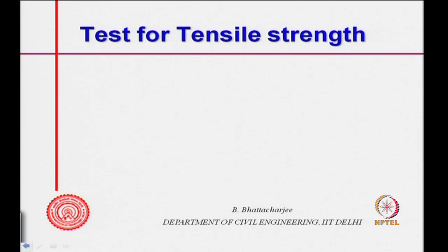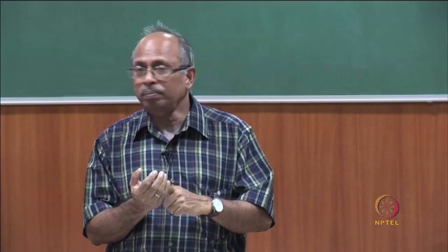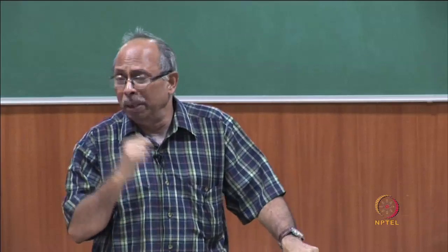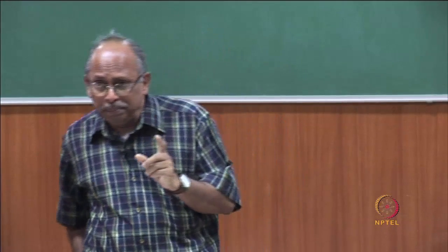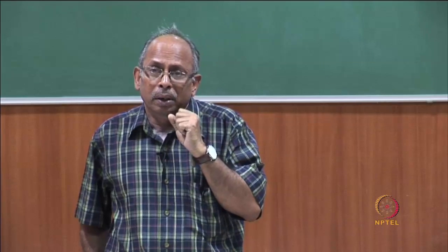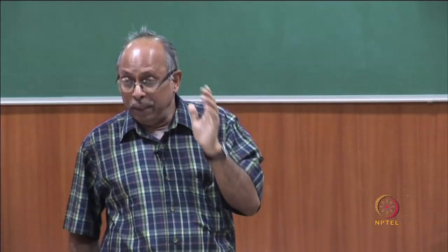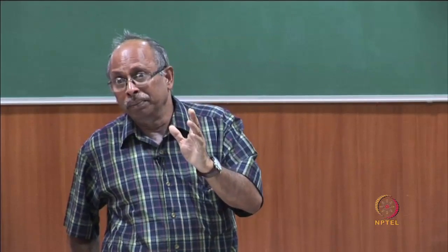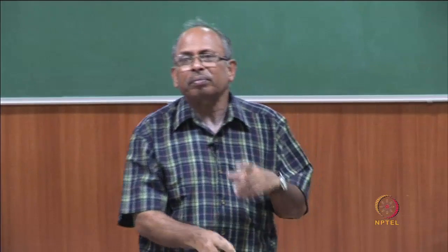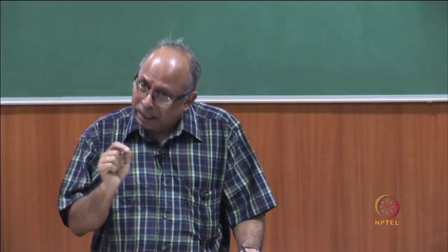So, what we have seen for the cube: first of all the capping and size, I mean the aspect ratio, L by D or H by D. Then we have seen the rate of loading, moisture condition, size of the specimen. So, all these factors affect the strength. Therefore, codes standardize those conditions,